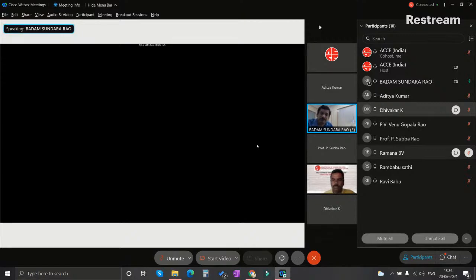0.009 into (liquid limit minus 20) gives your Cc value. That Cc value is the governing value that governs the compressibility of the soil, especially in the case of clay. What you require is the stratification of the soil, the different types of soils, and the depth of existence, and also you require both strength and the soil settlement characteristics. Strength characteristics are nothing but the phi value and the gamma value, that is the unit weight, and you require the Cu value in the case of a clay soil substratum.